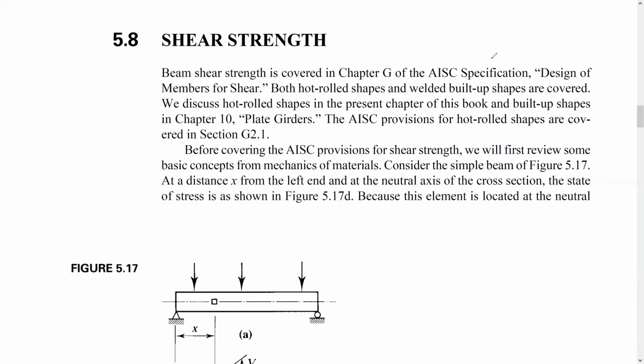Today, inshallah, we're going to continue with the flexure beam, and we will teach you how to check the shear. Usually, guys, shear is not a big deal or a problem for beams. So for that, the usual practice is to design the beam for flexure strength and then check the shear and the deflection.